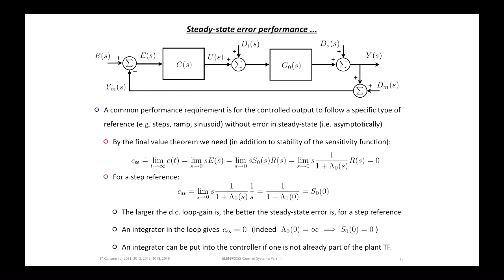All right, before looking at stability in a little bit more detail, let's just see how we could use some of the tools that we've seen in part 2 to understand the behaviour of a closed-loop system in steady state. We often assess the performance of closed-loop systems in terms of the response to particular types of signals. Like in the example we just saw, this was a signal like a constant plus something that had energy concentrated in the frequency band 0 to 4.